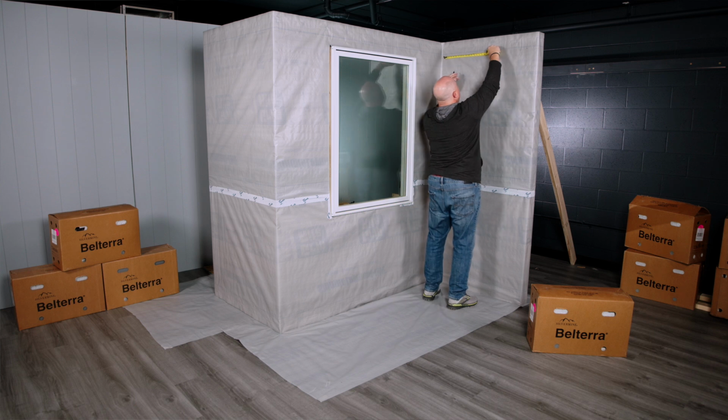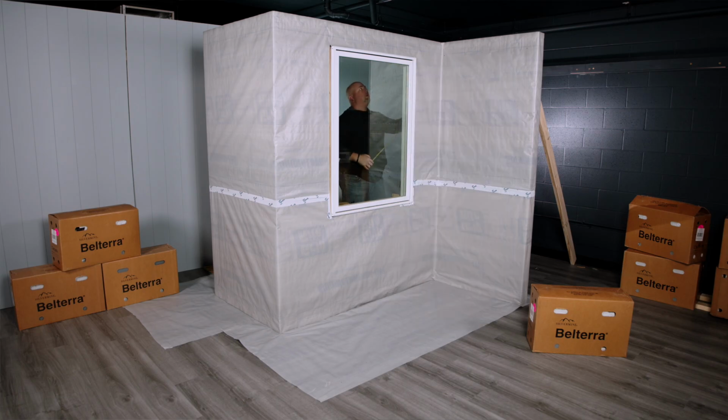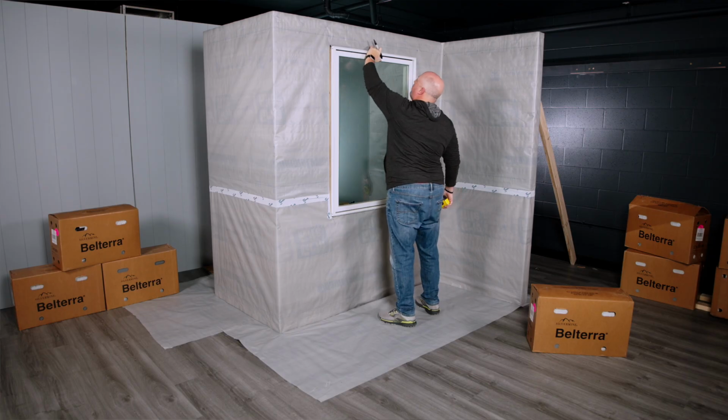Silvermine Stone's panels should be applied over wood framing, spaced 16 inches on center, that has been sheathed with 7/16" OSB or 1/2" plywood sheathing. Consult an architect or building engineer for wall design requirements on applications over 30 feet in height.